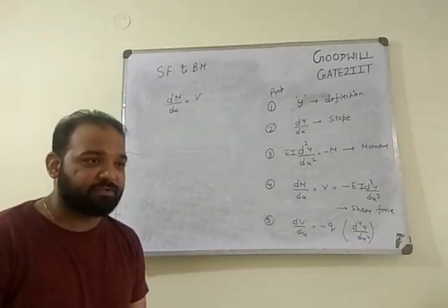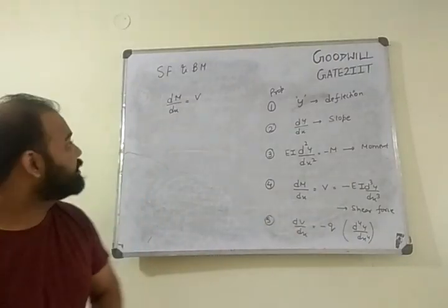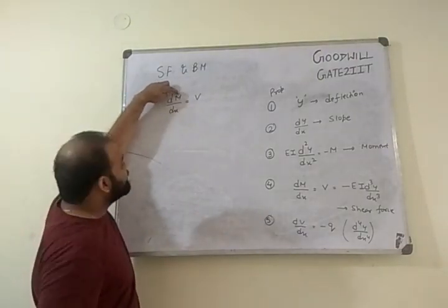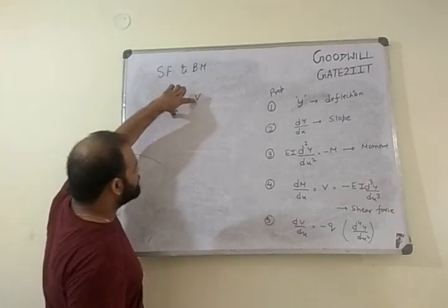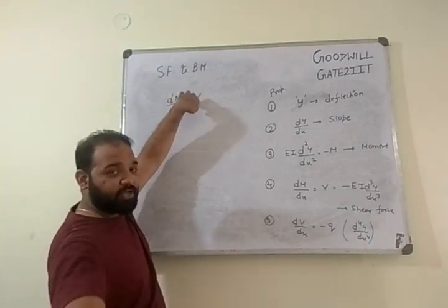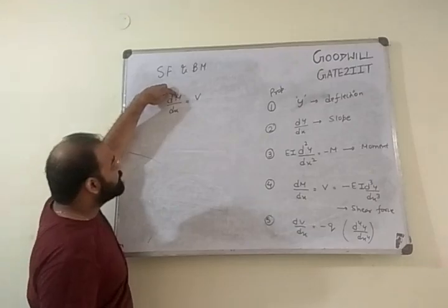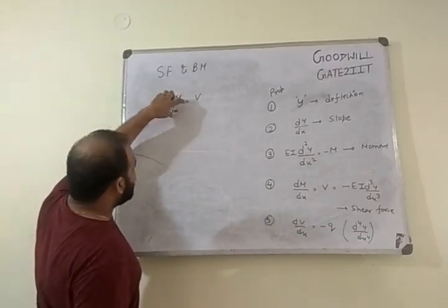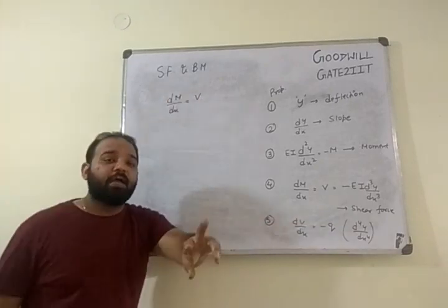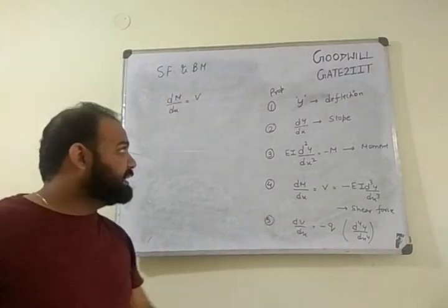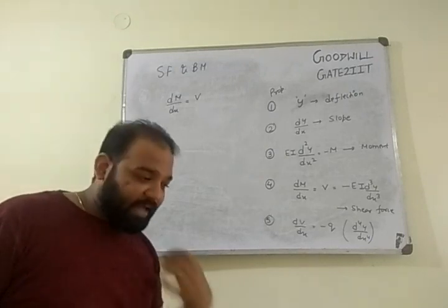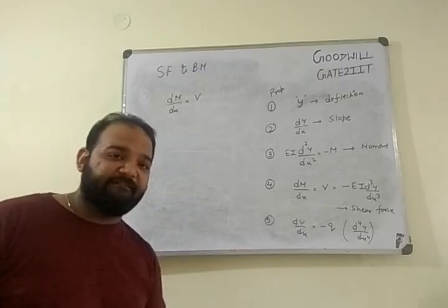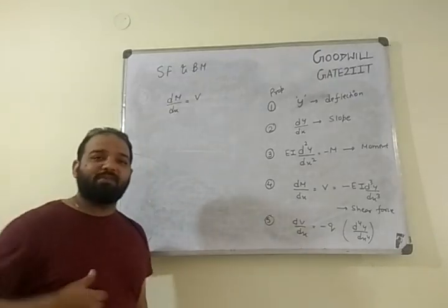When you have any shear force diagram, your moment is of higher order. Now what do you mean by higher order? If your moment is linear, let's say a function of x, when you differentiate a function of x with respect to x, you're going to get a constant quantity. Check your diagram 1. When you have your moment as square terms, x square, parabolic behavior, when you differentiate that, you are going to get linear terms. Check your simply supported beam with UDL or cantilever beam with UDL. So what I am trying to say is shear force and bending moment diagrams differ by one order. The bending moment diagram is always one order higher.